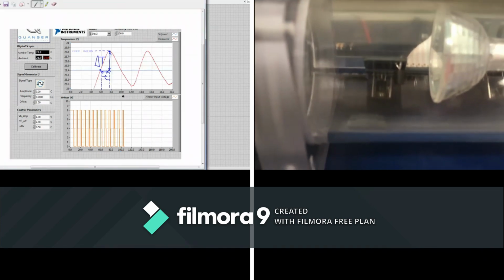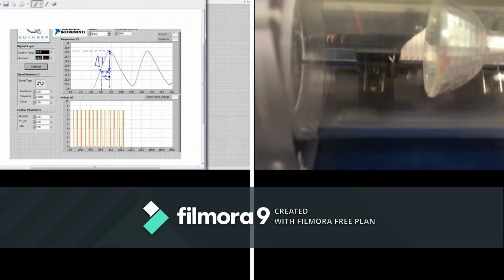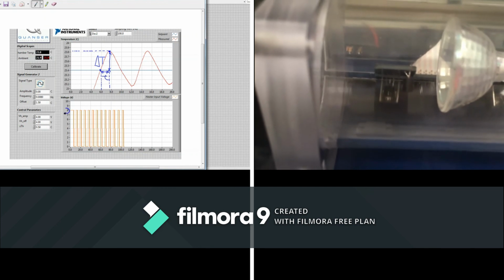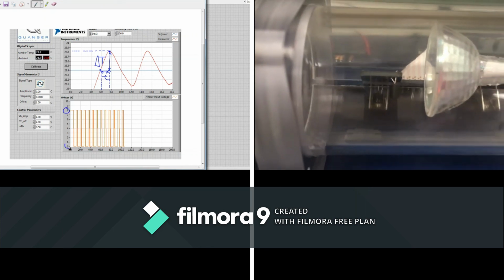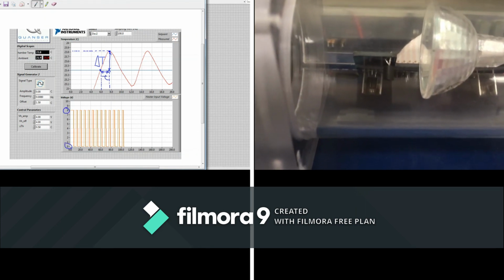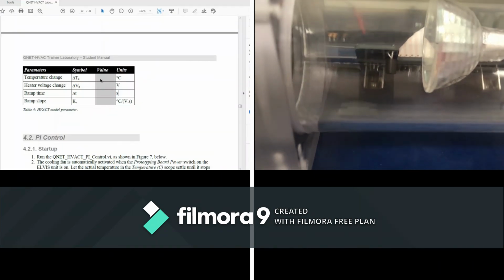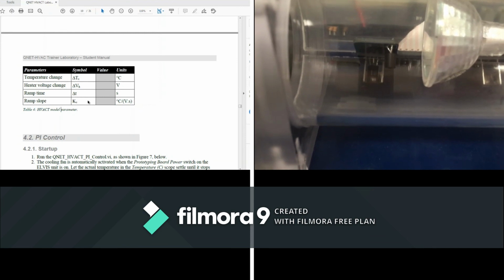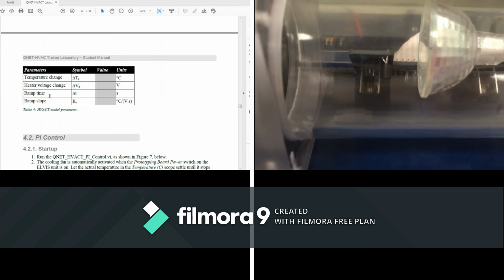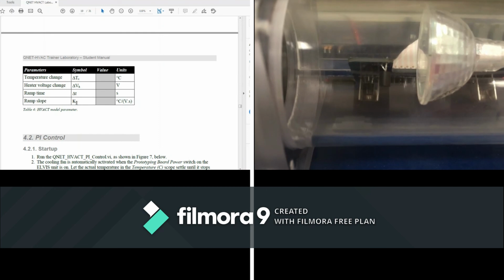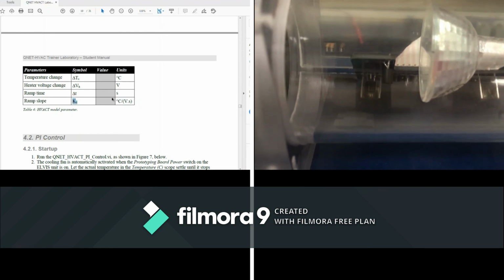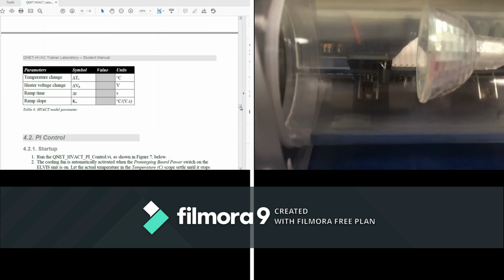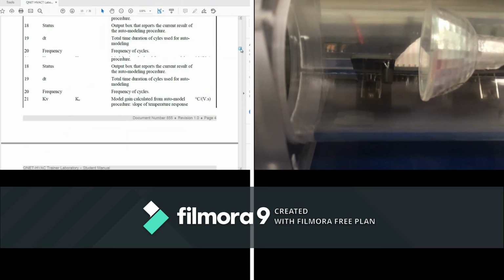So if I'm able to calculate delta T and the time, and the voltage difference, it's 8 minus 0, this is delta V. So simply I will put this value in here and calculate the value of K, which will represent the model of the system. So this system has a gain K of a value that we calculated, and this is our objective of this experiment.